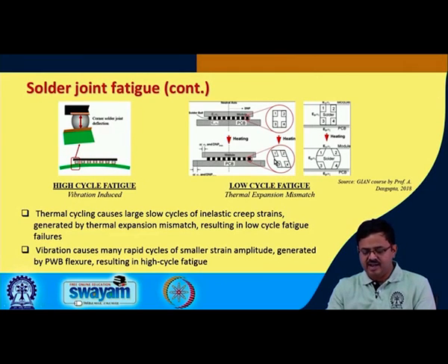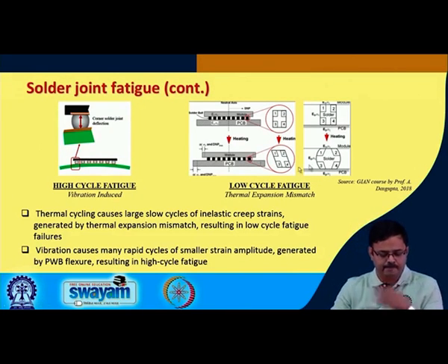But on the other hand, in reality, if you look even within the solder joint or the solder ball, if these are the four corners, you see the four corners are going to undergo stresses differently. So, we need to understand these. This will see more strain, this will see more strain, these two not so much, 2 and 3 not so much, 1 and 4 much more.